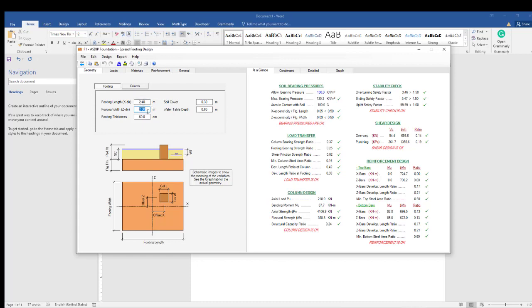Now let's see if we use just one side, and it changed quite a bit. So now it's 100, which is quite good for this allowable, and we got 109. Even for a high safety factor, this stability check is very high. So we can make it 220, and this is 130, but the uplift safety factor is very low, so it's better to use an even larger one.